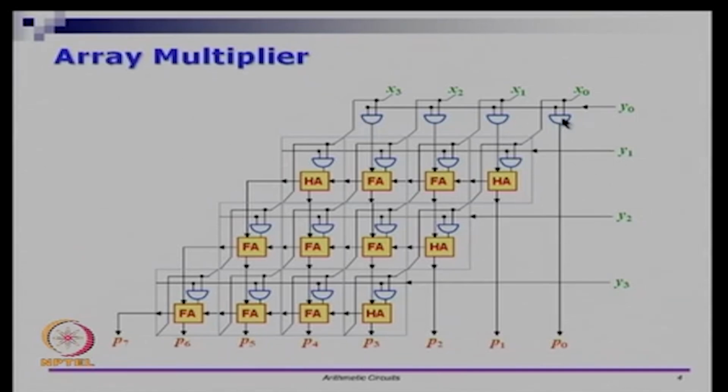You continue doing this for each and every step. So, the very first stage is just AND gates. In every partial product stage, you put this circuit here: half adder, full adder, and half adder. I guess this must also be a full adder. So, that is a mistake here. Okay, this is not a full adder, it is only a half adder. So, this is fine.